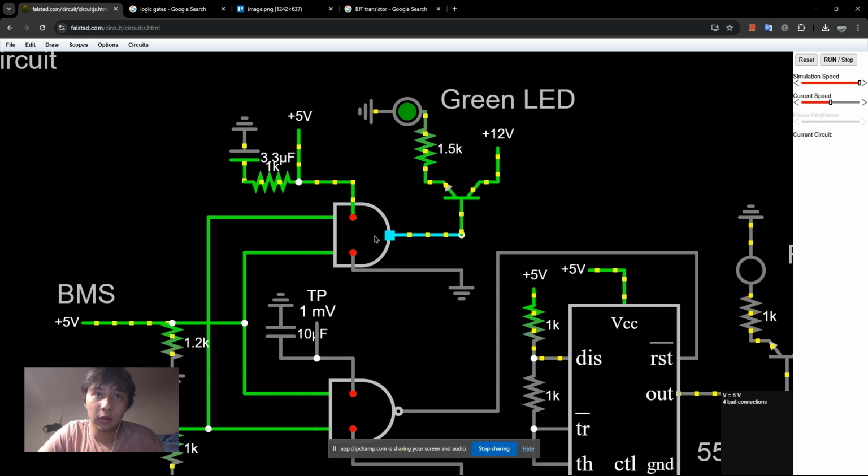So over here we have current, although it's moving very, very slowly. You can't see it in the simulation. There's current along this base wire, and it's connected to this transistor. So it's telling the transistor to turn on, and what that does is the voltage supplied from this 12 volts will go through this collector wire and into this emitter wire, where it'll power on the green LED. And this base wire will just tell it to let this collector current pass through.